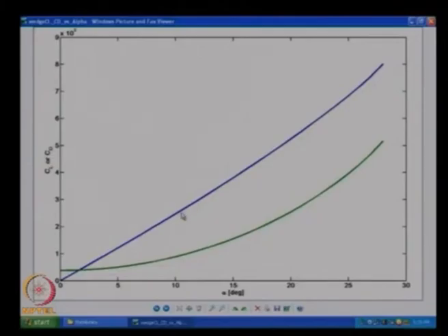The top surface shock will just jump, and the numbers are crazily high here, CD or CL. I think there is probably some mistake here. I think I didn't divide by the correct dynamic pressure, with wrong units. The curve is this, but this number is too high for this to be. It cannot produce more than the dynamic pressure kind of lift and drag. So I think there is some mistake. Probably it is absolute values of lift and drag and not CL and CD. I made a mistake there. It is for Mach 2, 1 atmospheric pressure, 300 Kelvin flow. That is what I have.